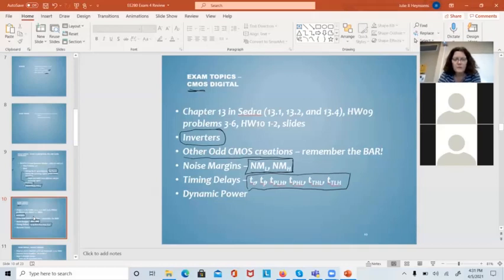And dynamic power is really important. That's one of the most basic things. The dynamic power basically equals the frequency you operate at, how many gigahertz your clock is, times the capacitance you have to drive, times whatever power supply you have squared. It's the rule that's been ruling the world for quite a while. We want to run faster, we got to lower the power. We got to lower the voltage supply to keep the power down, to keep from melting these things. This is probably where most of the focus is right here, as for points on the exam.